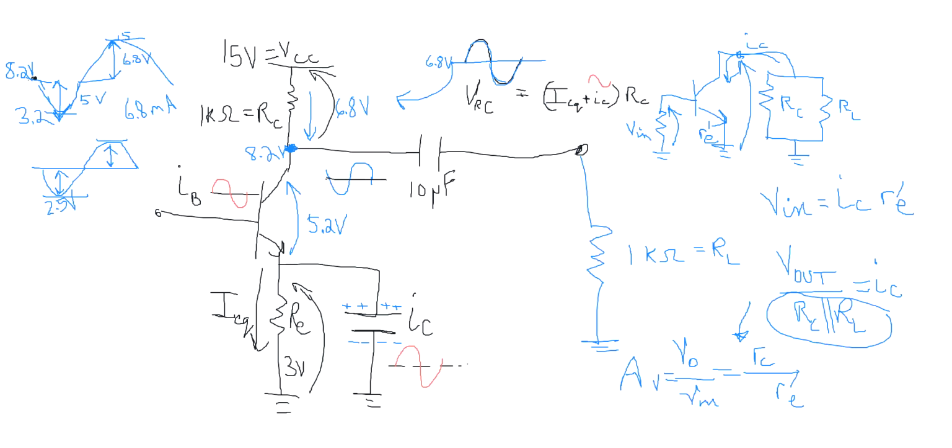So there is one final point that we will make, and it's an important one. Notice that we squashed the sinusoid at the output when we added the load. That's an important result, because remember this floor we had of 3.2 volts because we couldn't get below the 0.2 volts here.